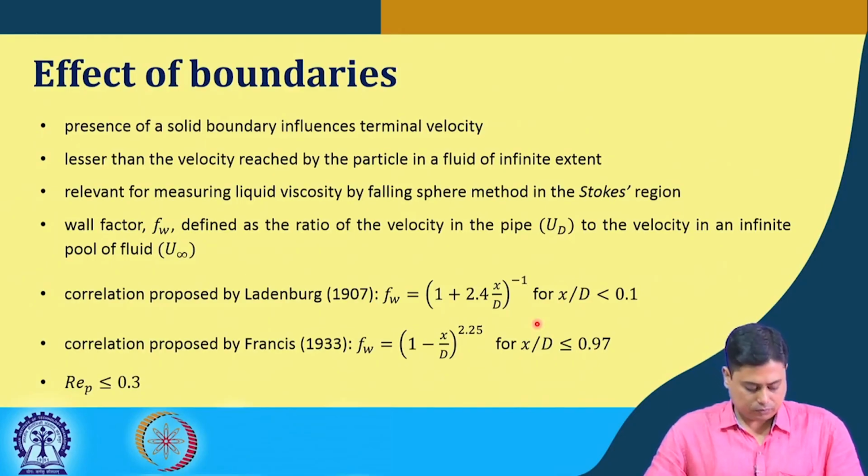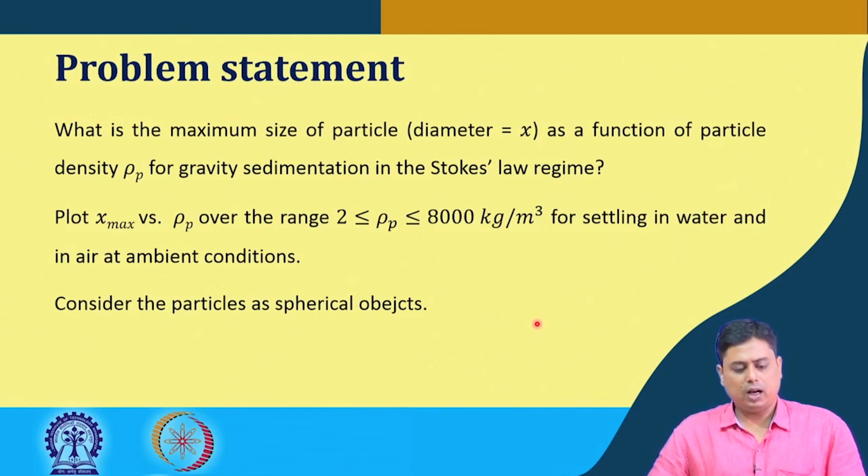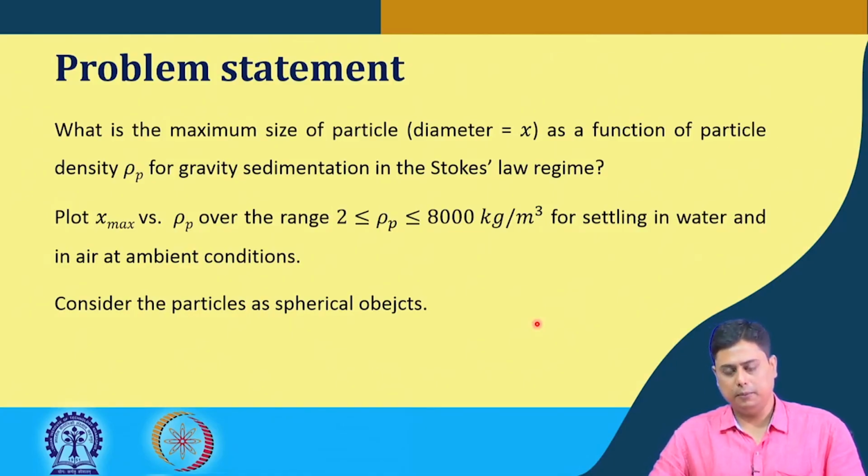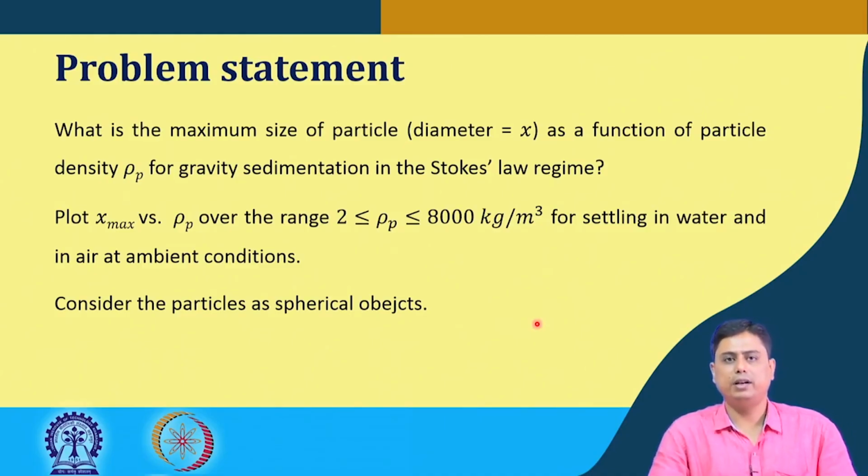Okay, so with this, if we quickly come to a problem statement to see how these ideas are implemented or how these theories can be better understood, if we look at this problem: what is the maximum size of particle as a function of particle density for gravity sedimentation in Stokes law region.